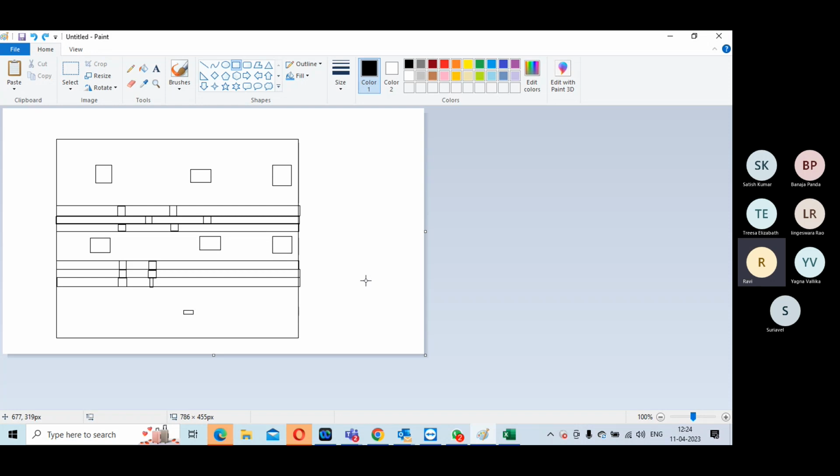AND isolation means the output should be following the input. That means the other one should be connected to 1 or something. OR means that the other input is supposed to be connected to 0 so that it has a pass through. Then how you are actually going to control the isolation is like that. Memory means it should store the previous bit. Yes, retention cells. So the previous data is registered, and that register should be connected so that the registered data is always maintained as the output.